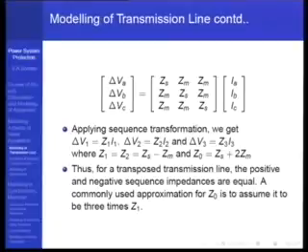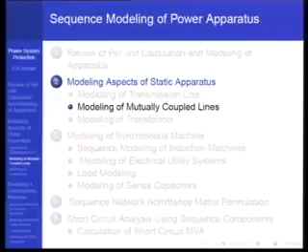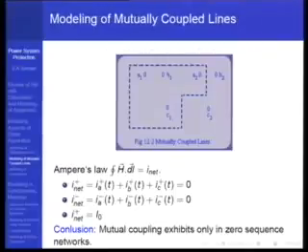If your design data is accurate, then your actual calculations will also be very accurate. But zero sequence values are under certain assumptions which may not be true in that ground, so a measurement will give you a more precise value of the zero sequence transmission line data. Another interesting thing which you need to look into is the mutual coupling.